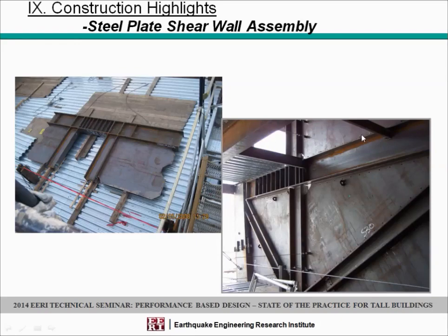There were several variations, and you see that on the diagram to the left. This is one of what's called the secondary vertical boundary elements, and you see the shear yielding link with all the stiffness on top of the opening. You see how they were able to assemble a lower piece and an upper piece attached to the steel beam, and that's how some of it was erected.